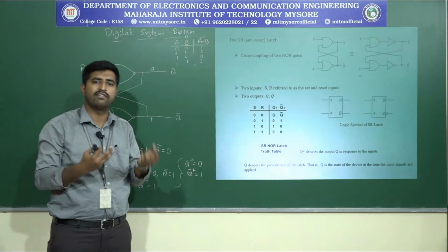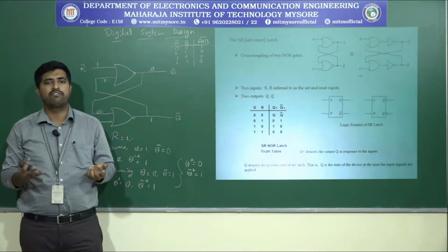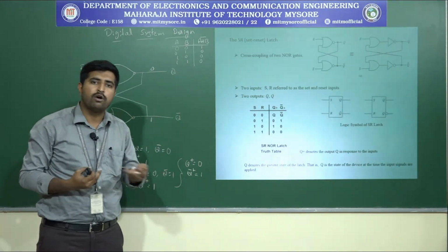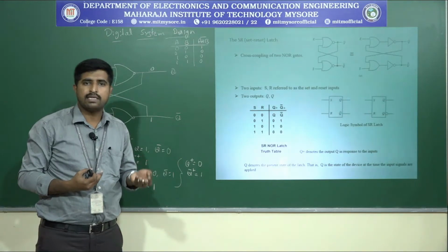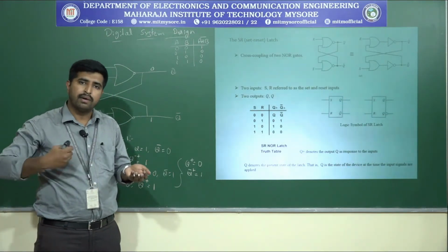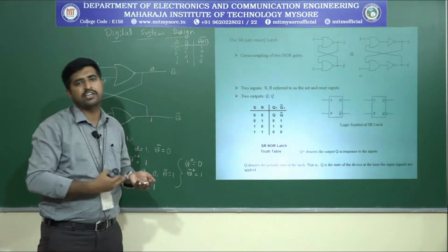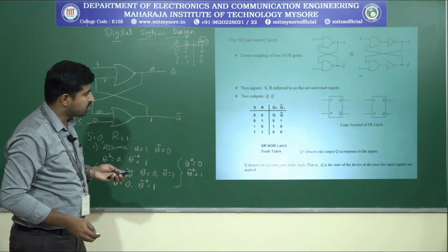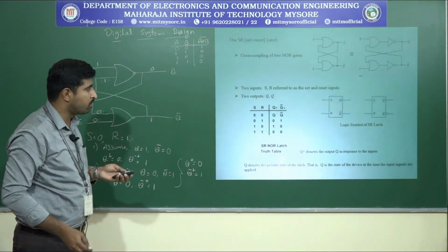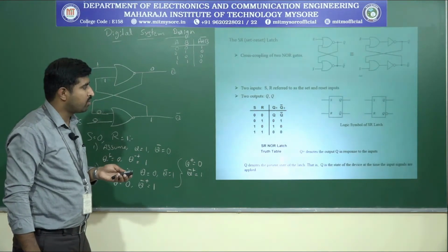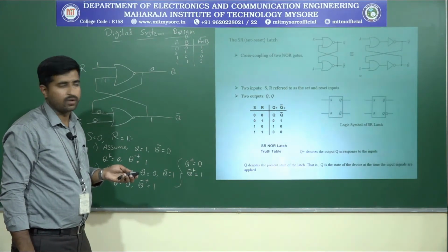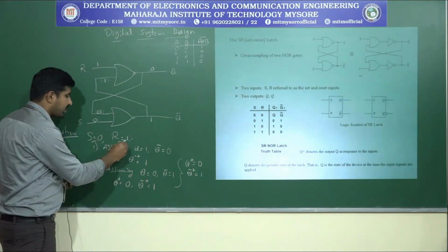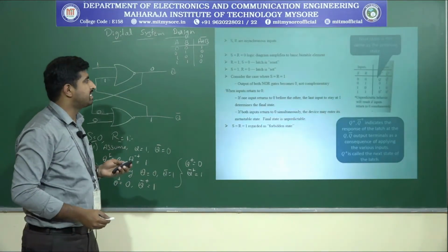That is the difference between the bistable element and the latch or flip flop. In the bistable element we are not able to force the output or the state of the element, but here, by applying the input, we can change the state of the latch. So when S equals 0 and R equals 1, Q plus always gives 0 and Q bar plus gives logic 1. This is the SR latch response for inputs S 0 and R 1, and this state is called reset.